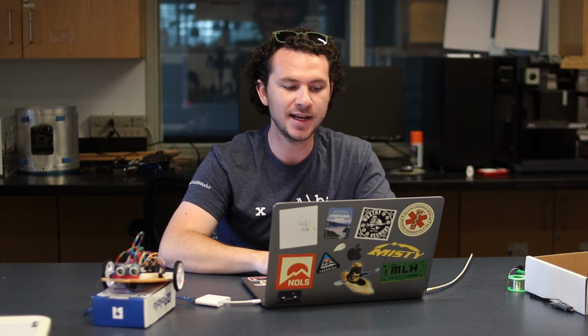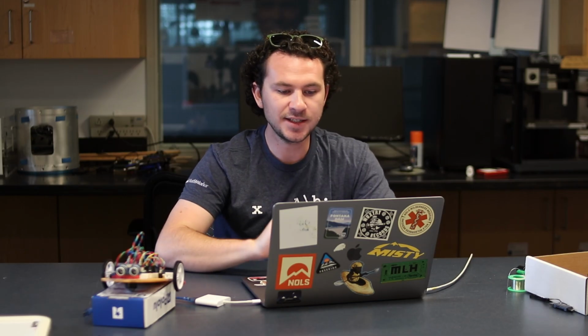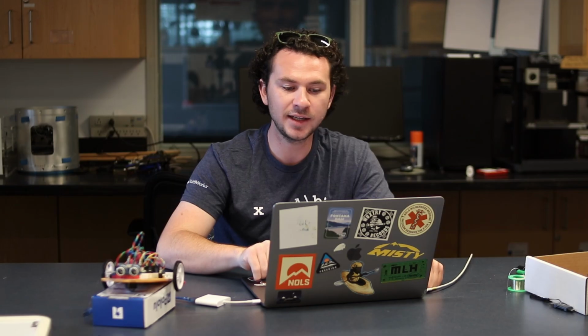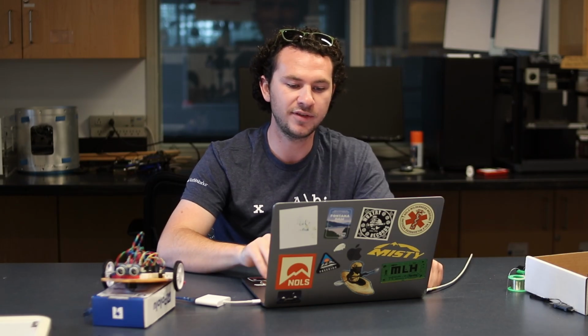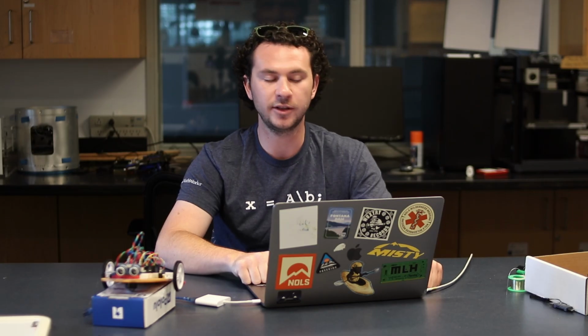All we need to do that is call ICM.begin_I2C to attempt to initialize our device. It isn't strictly necessary, but we're also going to add some simple error handling logic that lets us know if initialization is unsuccessful and enters an infinite loop so the program doesn't go on any further.